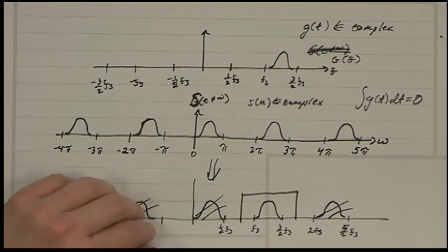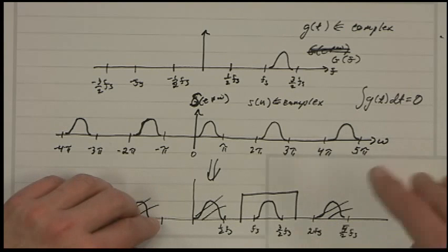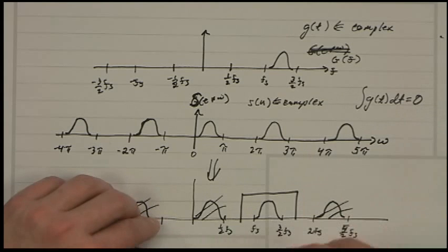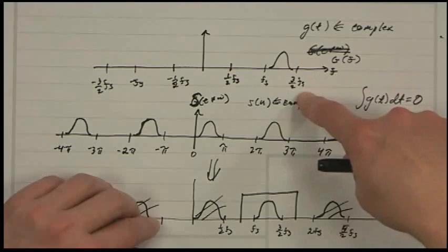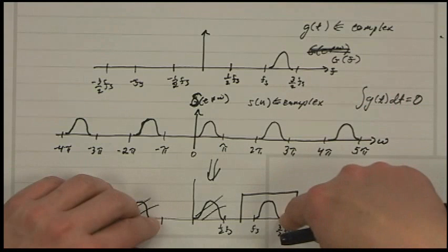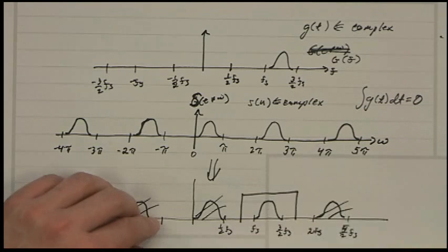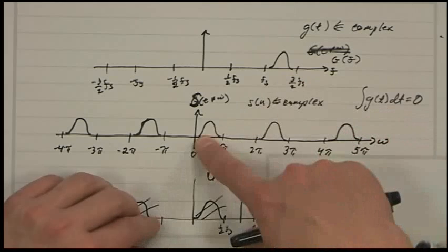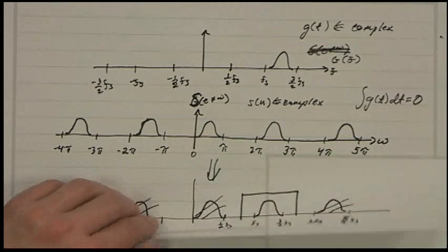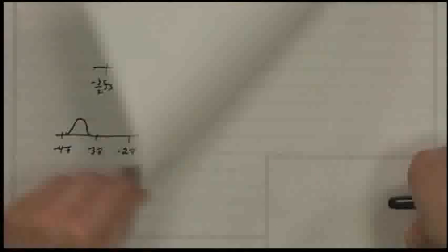But when you do that, then the carriers have to be coherent and precise, or you'll get phase errors, which may or may not be important. If it's a communication system and you've encoded information in the phase, then that would be important. So this could be like a, what do you call it? A relay, not a relay, a repeater in a communication system, where this was a modulated signal and it took it, sort of demodulated, amplified it, and retransmitted it. It's kind of interesting. It does come up.